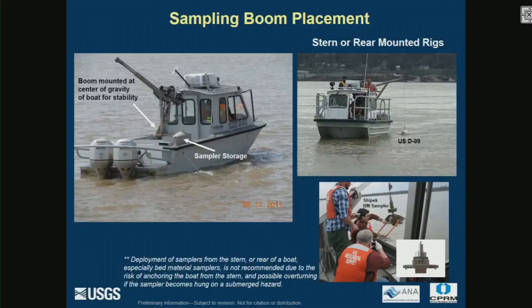They're capable of doing this, but in sampling bed material off of the rear of a boat, if that sampler were to become connected or hung on a hazard on the bottom, a tree trunk, a sunken boat, some sort of concrete where you could not get that sampler back up, what happens is you become anchored off of the stern. And you don't anchor boats off of the stern, you anchor off the bow. And so any type of bed material sampling, if at all possible, should be done off of the front of the boat. And I'll show you another setup.